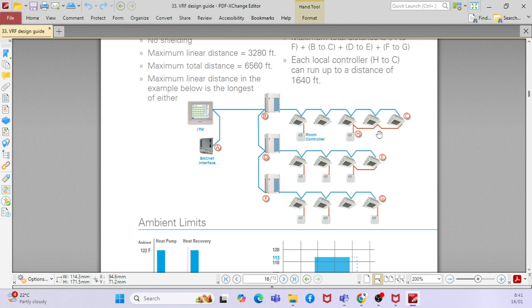Say for example, there is a building. Maybe you want to go with an air cooled chiller. When you calculate the total building load, maybe you have 4 or 5 air cooled chillers, but there is no space to keep them on the roof or at ground level, or when you keep them on the roof level, your structural load cannot bear the chiller loads. So that is also one of the factors. We have to see, then we have to decide.